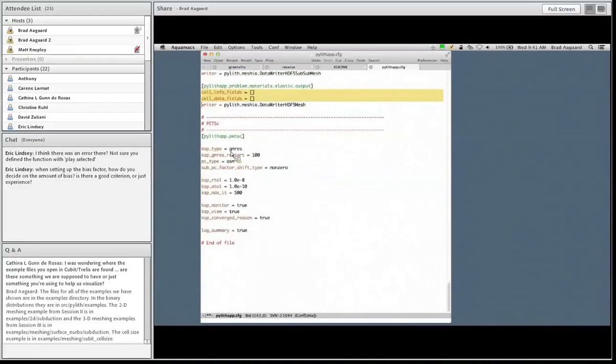Now let's look at our fake data. This is going to be the simulation for generating our fake forward simulation, fake observations. So this is limited essentially to just the fault and the output. We're going to use a kinematic fault for prescribed slip. Then our slip distribution is in the file eqslip.spatialdb. It has a linear variation. And for our slip time, we're going to use a uniform database.